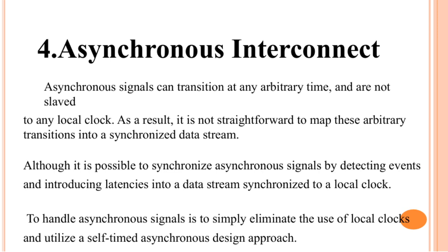However, a more elegant solution is to avoid using local clocks altogether. Instead, you can adopt a self-timed asynchronous design. This means the system regulates itself without relying on a global clock, allowing it to handle asynchronous signals naturally and efficiently. This approach can simplify timing issues and improve robustness in some circuits.